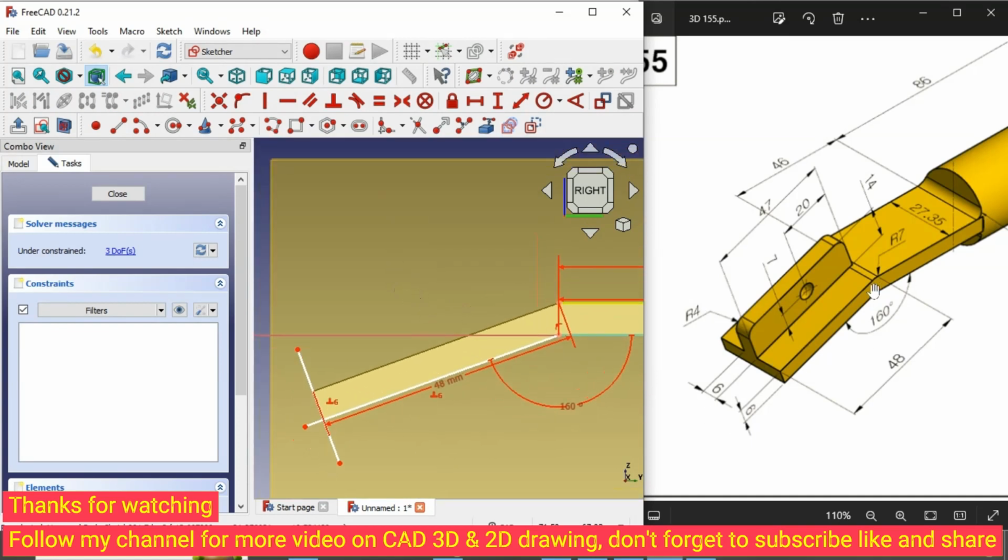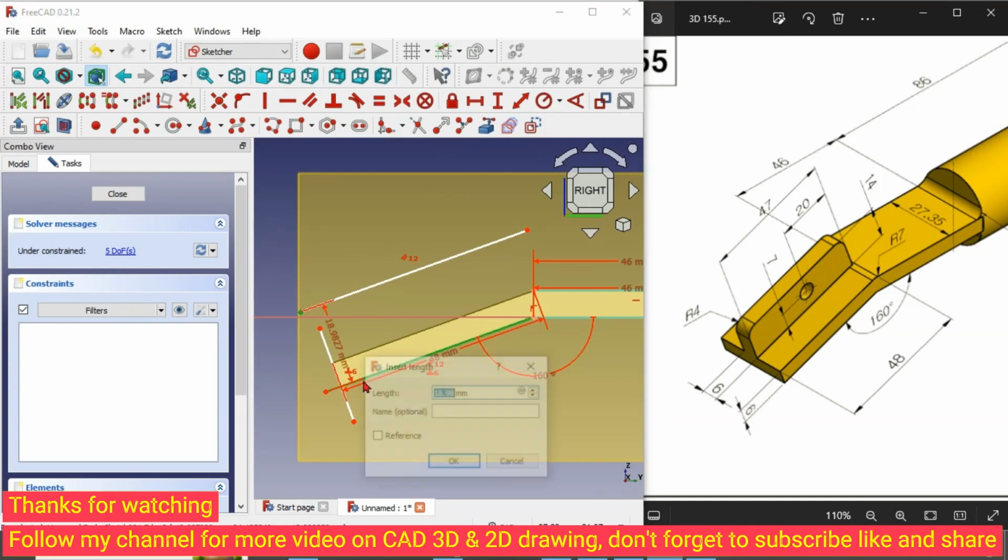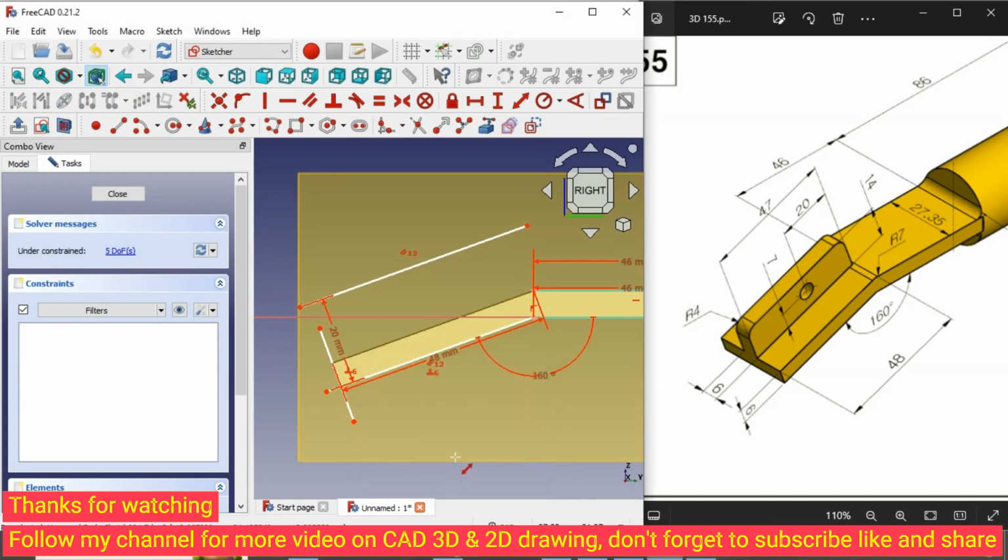okay, the thickness here is 14. From this surface to here is 14. Then we draw a line here. We make sure this line is parallel to this line. Then we set the distance. This line to this line will be 14. 14 plus 6. Because 6 is here and we have another 14 from the surface, so 14 plus 6 we have 20.